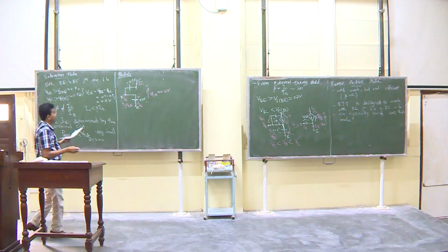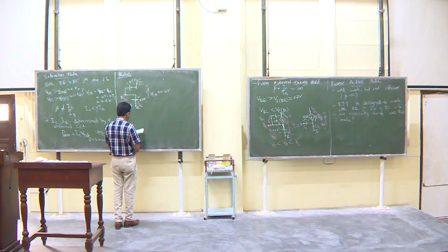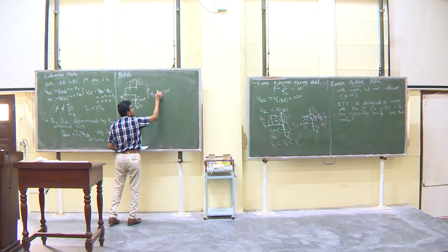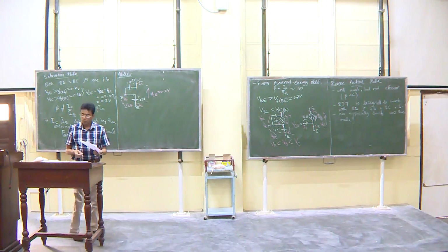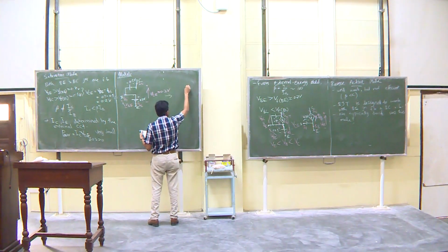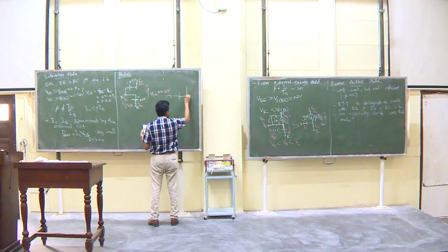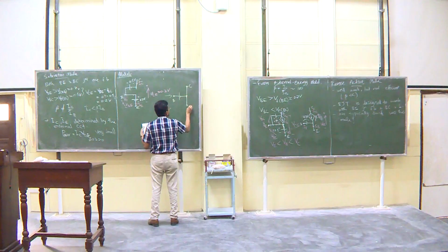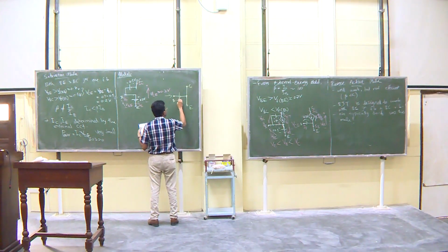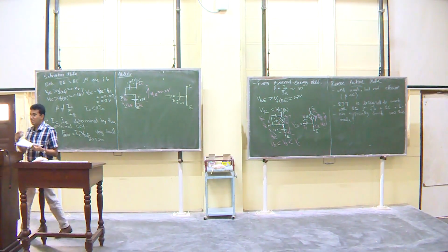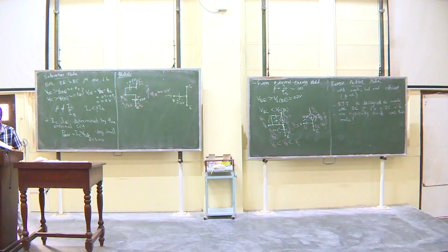So, combining this, sometimes, if this value 0.2 is too small, if we are working with larger voltages, we can even simplify and ignore that and get something like this, the simplified version. Okay, base, collector, emitter, this is 0.7. So, in that case, we simply ignore the 0.2 volts there. Okay. That is a simplified model.